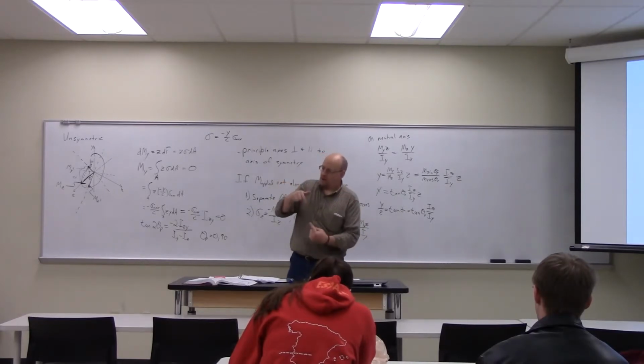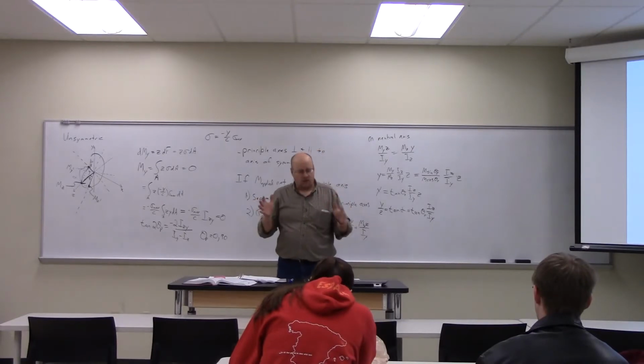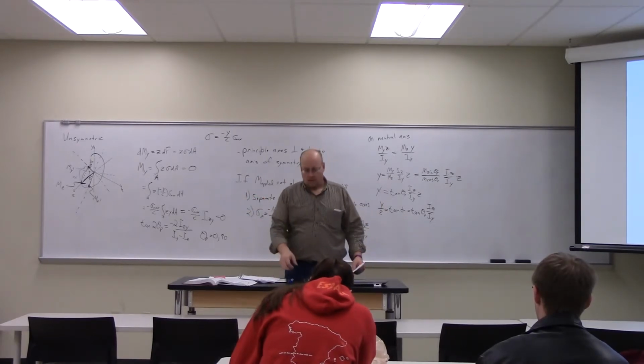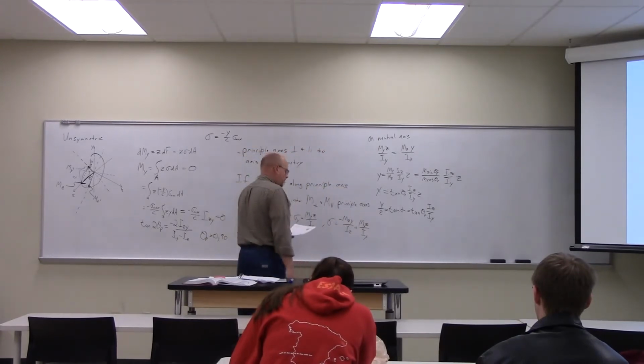That strain creates a stress in the other direction as well. So even though I'm only applying a normal stress, there's still a Poisson-induced stress from the lateral strain in the material. So it's all interactive, and there's basically a 6x6 matrix that describes the total response of the material. But we don't want to get into that now. That's an upper level course.